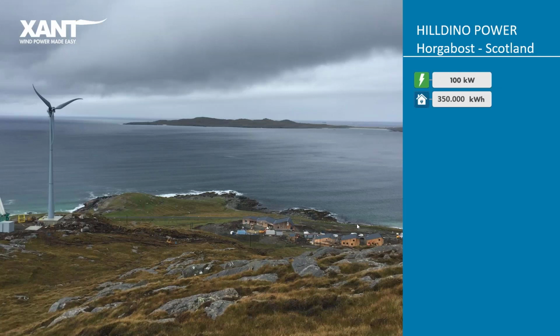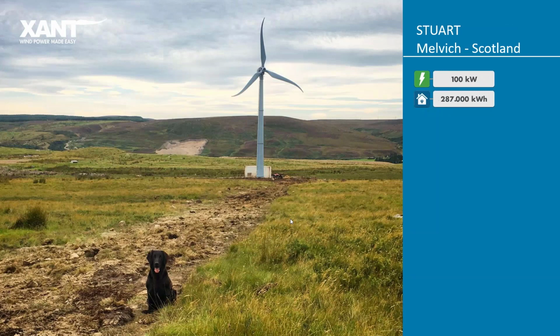This is a near off-grid solution where the grid connection was very weak, and the community needed a higher load. So they have a 100 kilowatt wind turbine, but they can only feed 50 kilowatt back into the grid. So the other 50 kilowatt needs to be managed locally. And there they used an interesting system of dumping the energy. One system, I'll skip this system, this is Scotland as well.